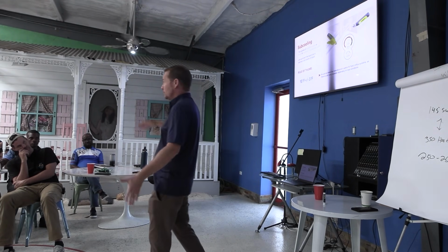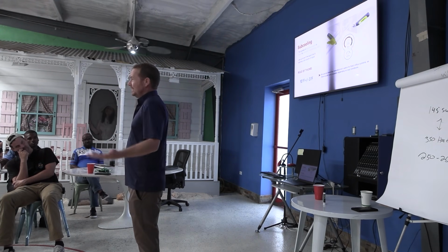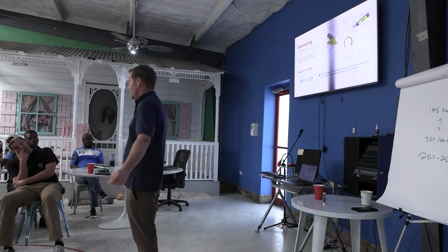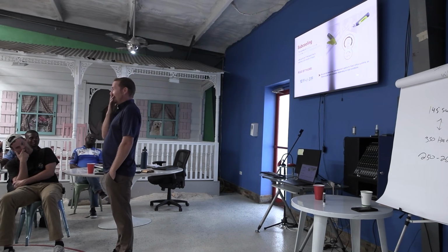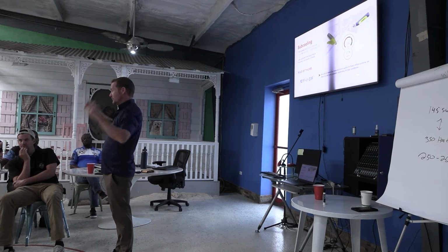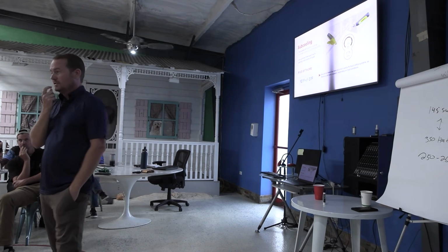In most cases, when you see really low compression ratios, really high suction, really low head, it's usually the compressor not pumping. Now, before the junior guys just say, hey, got a bad compressor, swap it out, right? Well, what's the mistake there? I'm going to let the senior guys dictate that. Well, bad compressor, swap it out, not pumping. What's the mistake? What do you need to do first?